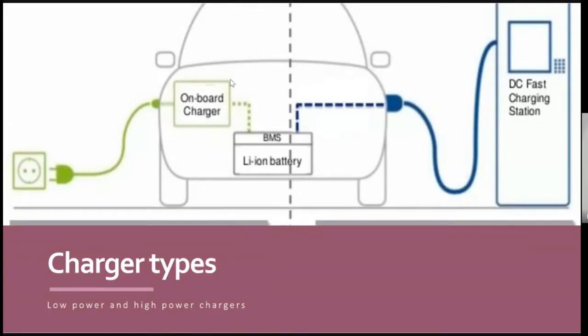There are communication standards. One charger type is CHAdeMO, which is made in Japan, and one type is GB/T, which is made in China, and one type is CCS2, Combined Charging System 2, which is coming from Europe. Mostly India is following the European standard. So power line communication is used in DC fast chargers that are planned to come into India. That means there are a lot of opportunities in DC fast chargers. A lot of communication should be done. That means from the charger itself, it should be communicated to the cloud for metering. In this area, there will be a lot of microcontrollers inside the vehicle and outside the vehicle.